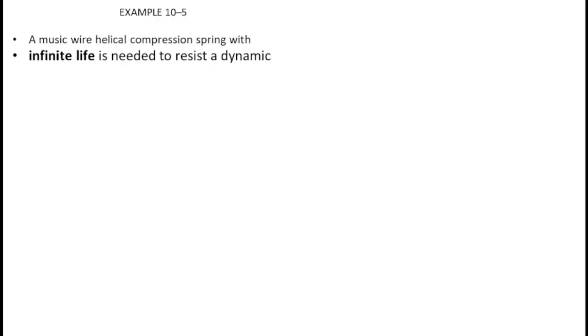Today the topic of our lecture is example 10.5. Here we are given that a music helical wire spring should be designed for infinite life, and the load that will be applied on this spring will be from 5 pounds to 20 pounds. 5 pounds will be the minimum force and 20 pounds will be the maximum force, and the frequency is 5 hertz.